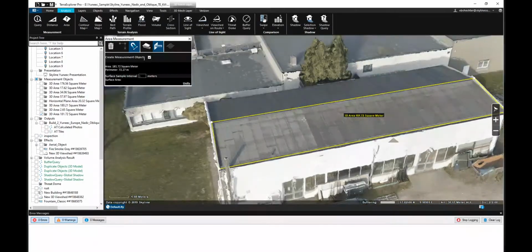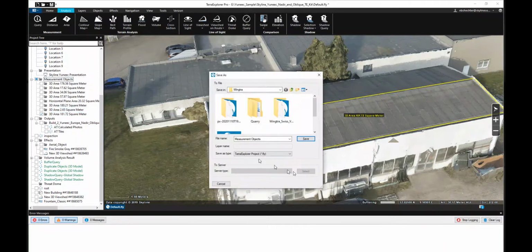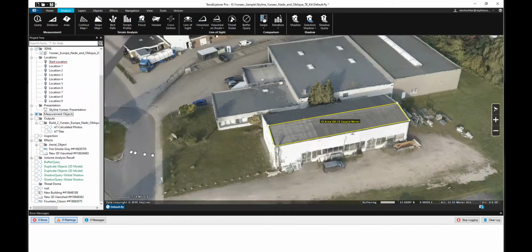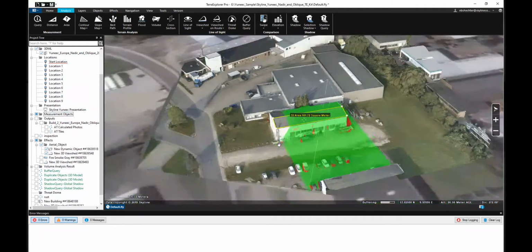If you have this option checked on, create measurement objects, it creates this as an object so that when the process is done, you can just export all of these into either a Skyline format, fly file, or a KML, a geodatabase, a shapefile. So everything that gets measured or done is accumulated and then exportable. The other options for the software, you could simulate an aerial object in motion, and you could also add a 3D model or a moving car on the road and represent it.